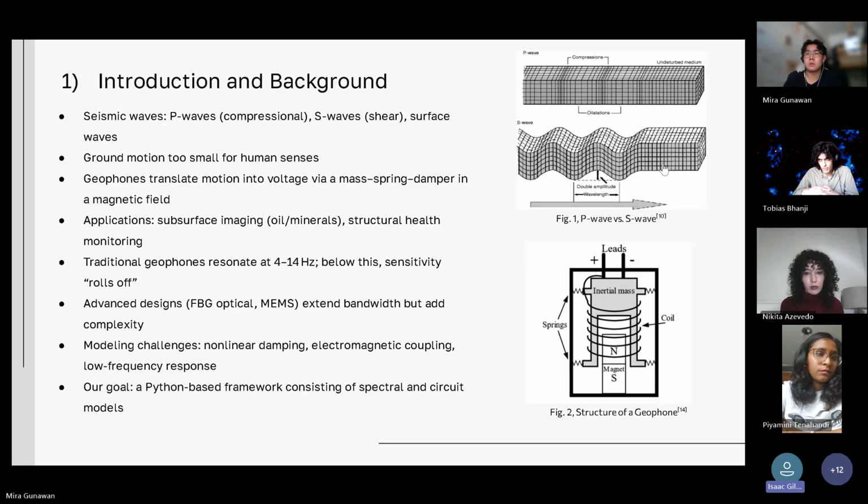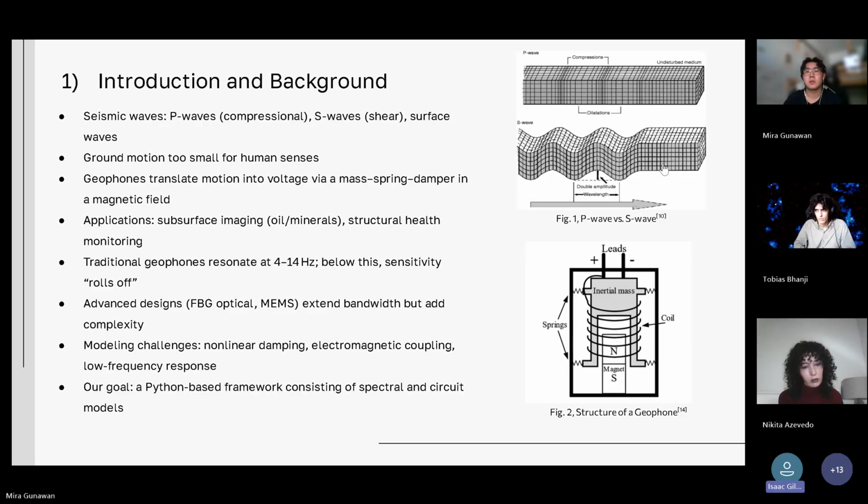While these technologies offer impressive performance, accurately modeling any geophone response remains non-trivial because real sensors exhibit frequency-dependent damping, mechanical nonlinearities, and electromagnetic coupling effects. Historically, engineering models simplify geophones as linear second-order systems, but even then, specialized circuit analogies, digital correction filters, and sensor fusion algorithms are required to improve low-frequency responses. For example, one source developed a SPICE-based equivalent circuit for a GS1 geophone and achieved amplitude predictions within 8% of the manufacturer's specs. Other studies apply inverse filtering digitally to extend usable bandwidth.